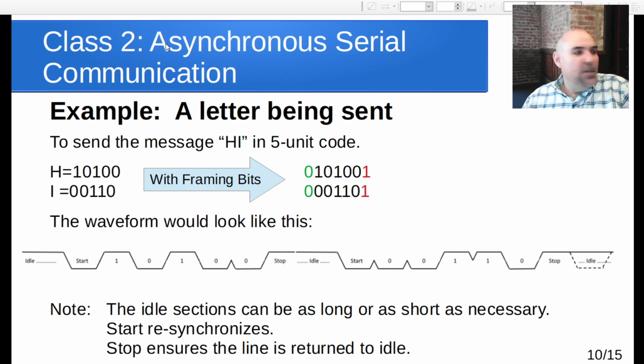Now that's a little bit of a misnomer, because notice there's still timing involved here. What's called asynchronous is basically saying they don't have to have the same shared clock. They're not using the same identical clock source or a physical shaft that they're both connected to. There can actually be some variation in those two motors and how fast they go.